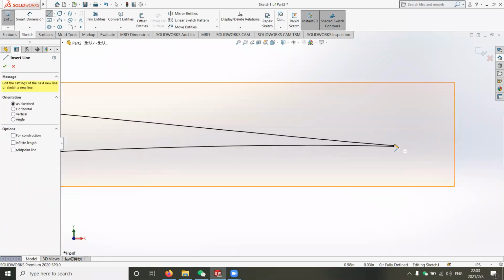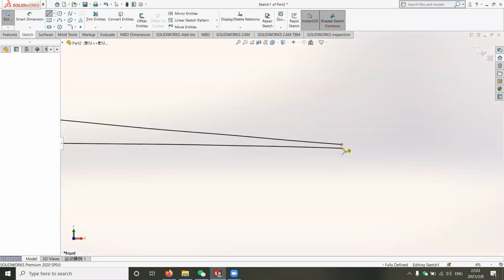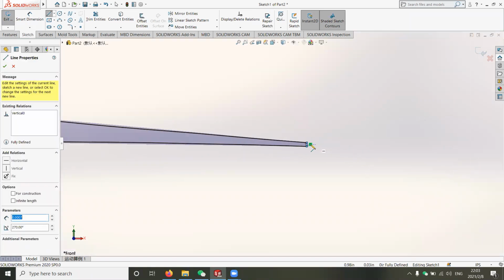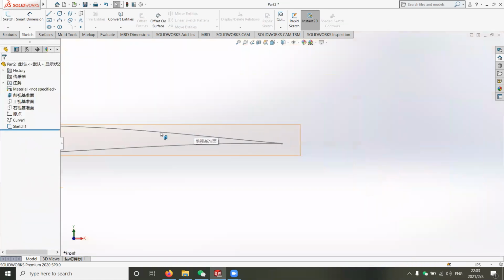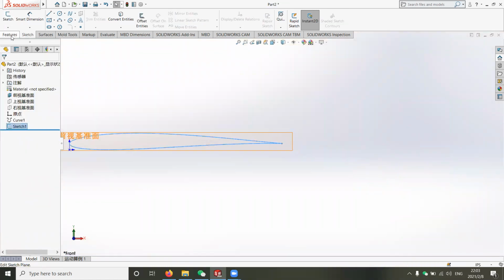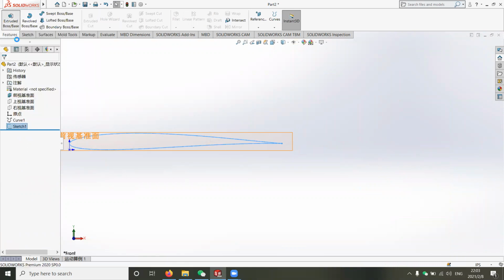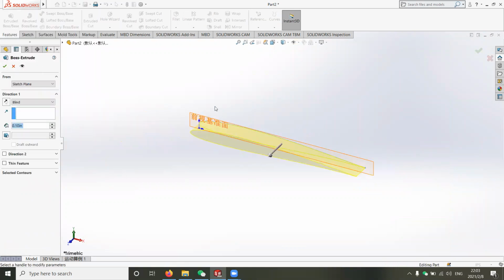In the sketch, you'll notice that at the trailing edge there won't be a closed contour. So you need to close the trailing edge by just connecting them with a straight line. And then we can do extrusion. So select the curve and then do extrusion. We want to generate a 4 by 8 inch wing. The chord right now is 1 inch, so we want to make sure the aspect ratio is 2. So you want to extrude it to 2 inches.